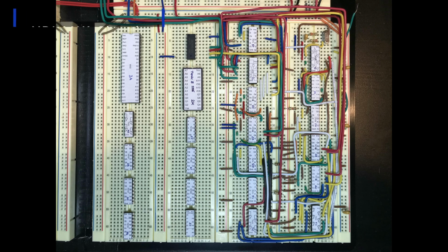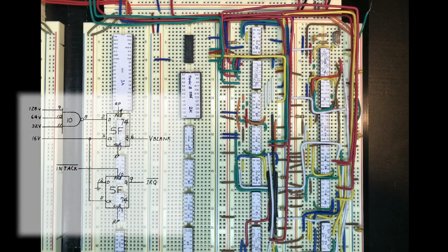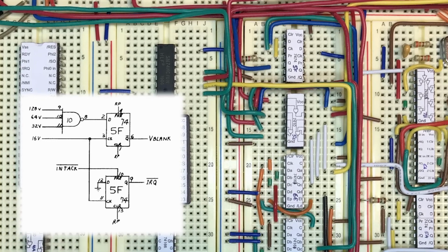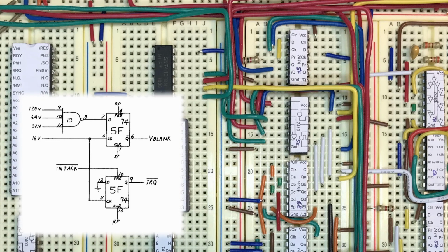Here's our circuit from last time. I've added a few things to get some patterns going. The first thing we need to add is the VBLANK circuit. That is the time in the vertical picture tracing that we don't want to allow anything to be shown on the screen. It's creating a black top and bottom border effectively.